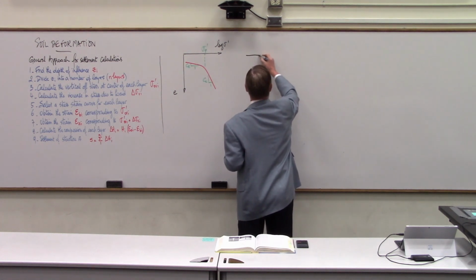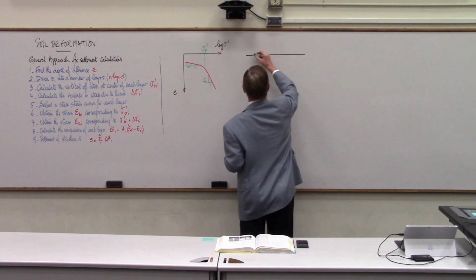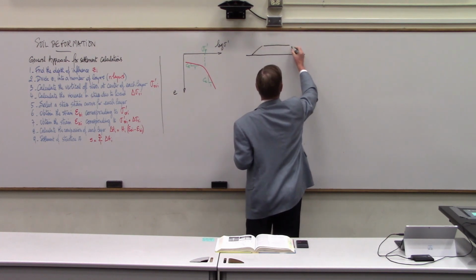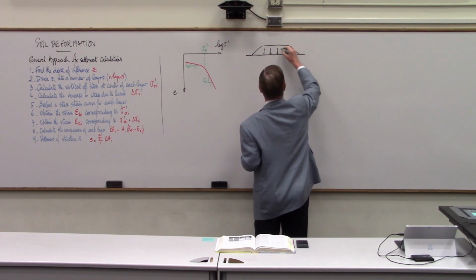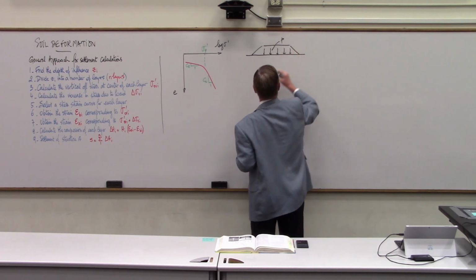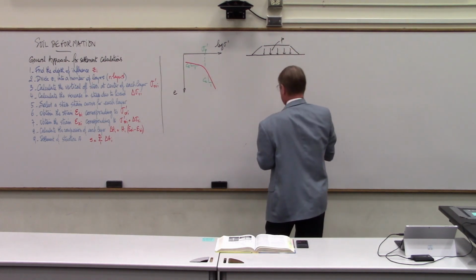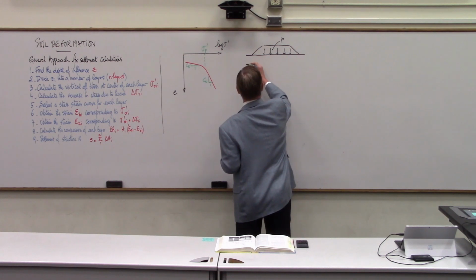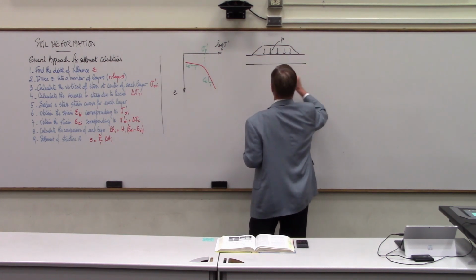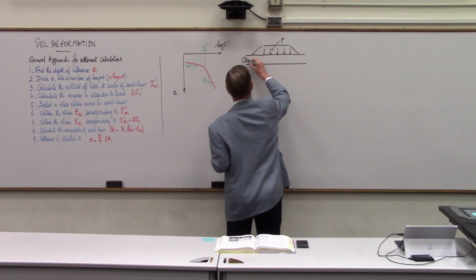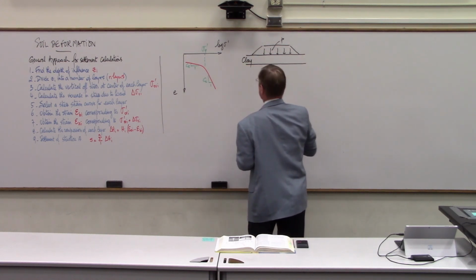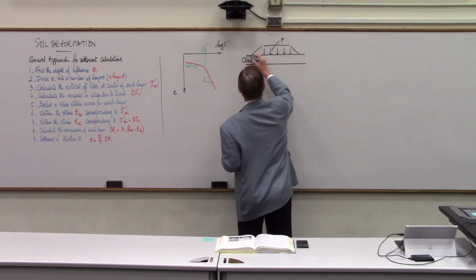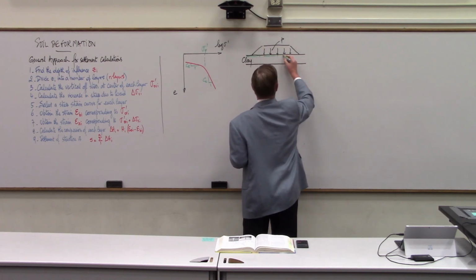So that's what we're going to have to be careful with. But let's say that we have a problem where we have an embankment here, an embankment that creates a certain amount of pressure on the ground surface, and then we have a fairly thin layer of compressible material, let's say clay, and the water level might be quite high, so the clay is saturated.